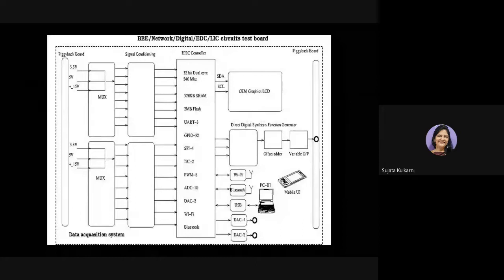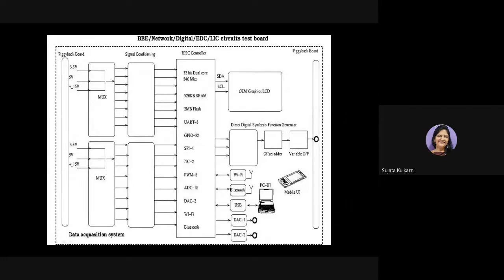So that is called signal conditioning, and that too for multiple channels, because as I said, we would like to have 8 analog inputs. Also GPIO, for example, for your digital circuit, could be another 8 channels. So at least 16 channels of ADC analog channels.